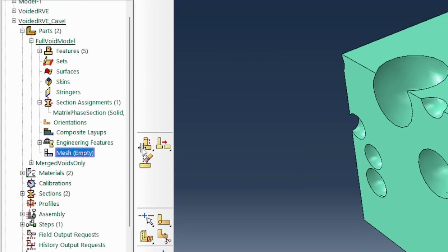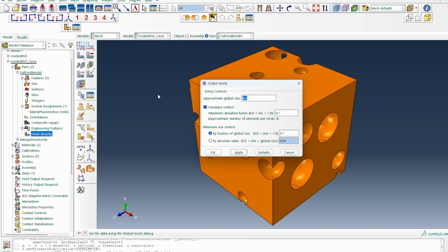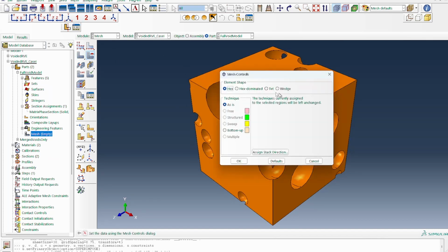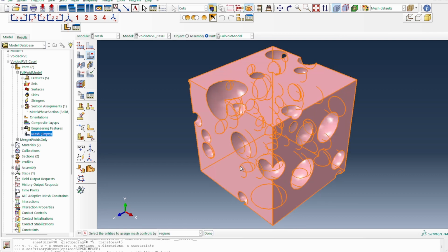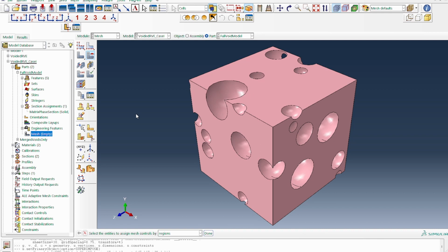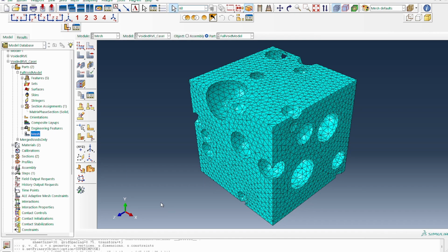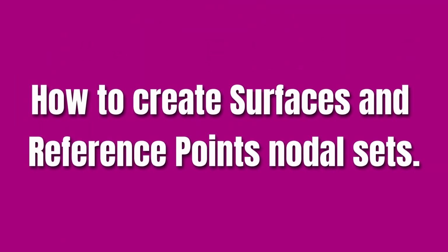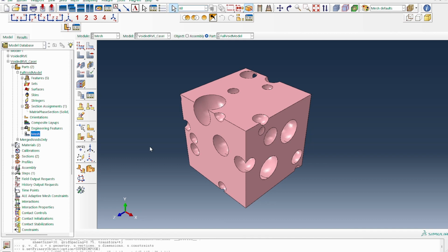Then you could try and mesh it. So if we try and mesh, I'll use what it's recommending as 0.4. And I could then ask it to use tetrahedron. Tetrahedrons are usually better because they will always mesh a system that is quite heterogeneous and complex in architecture this way. Then we can go ahead and merge the model. So the model looks okay, but I'm going to turn off the mesh at the moment as I keep working along.